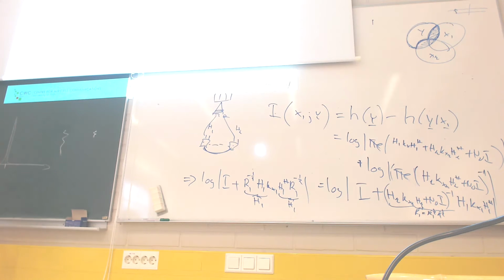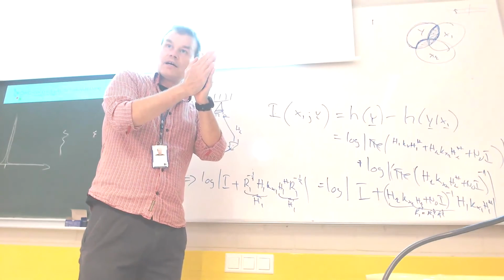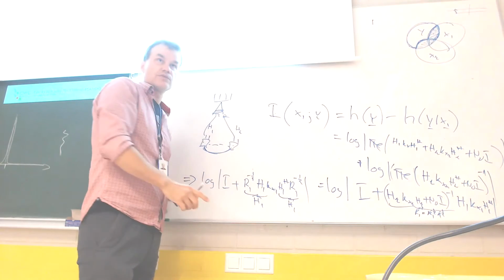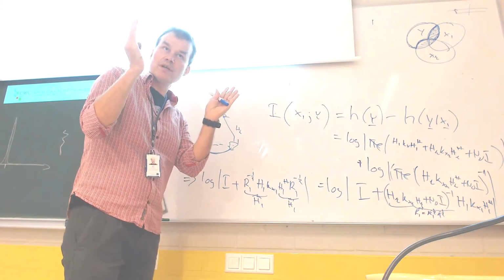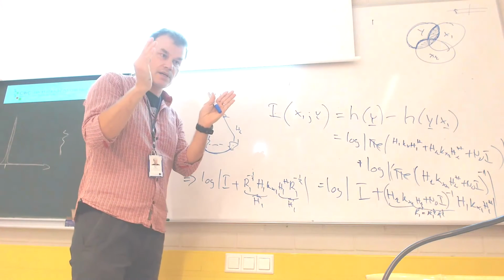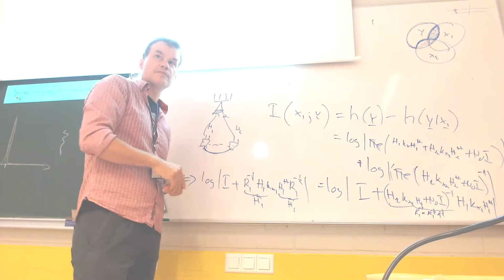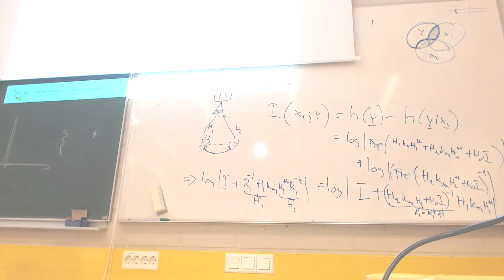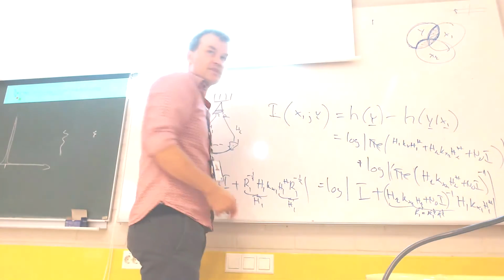Makes sense? User 2 is there as an interference, so you have to use some pre-processing. If channels 1 and 2 happen to be highly collinear, this will be a huge loss, right? You try to whiten it, but if they happen to be fully collinear, then this goes to 0. And similarly for the other decoding order, you get the same expression, just change the indexes.